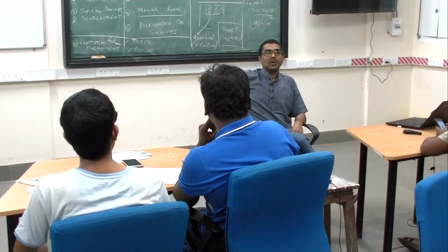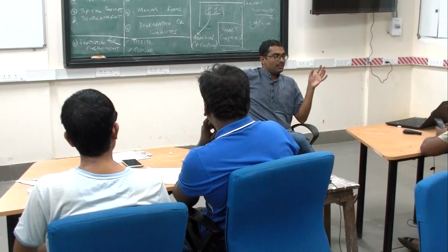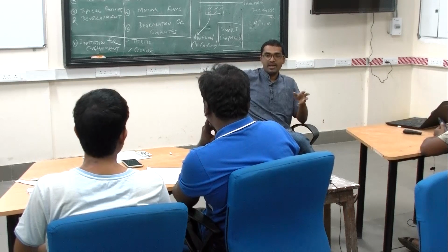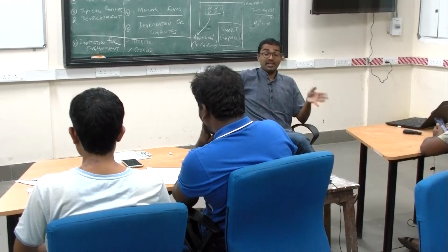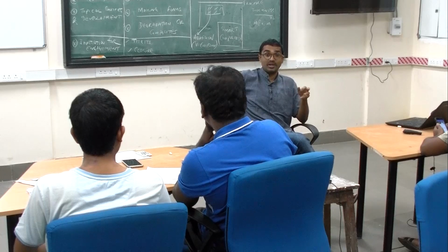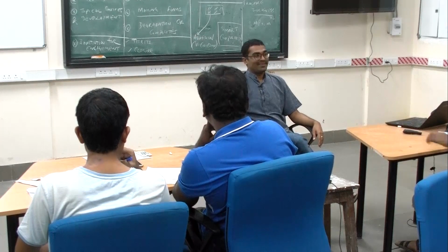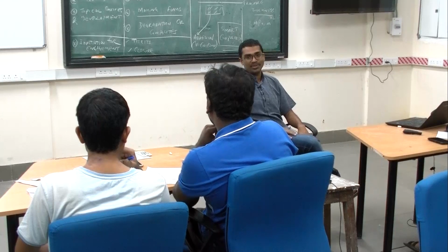This, by the way, you will also see in thermodynamics, isn't it? Wherein you have, let us say, enthalpy associated with a phase A, and enthalpy associated with a phase B. The enthalpy of the mixture will be xa Ha plus xb Hb, where in this particular case xa and xb would be the mole fractions. But if they interact with one another, there will be an xa xb parameter, which is by the way called the regular solution interaction parameter. So you will see that in something like a materials thermodynamics course and so on.